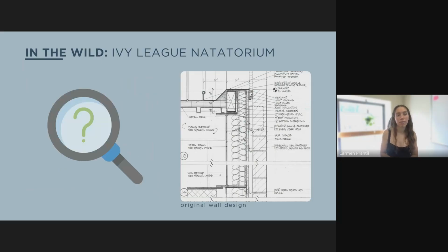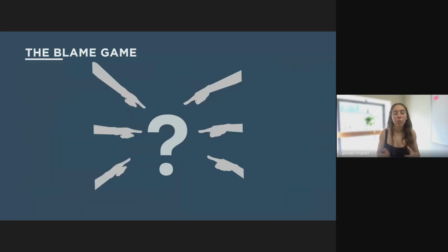So in terms of the primary contributor, which barrier do we think that this one was? So this one's going to be thermal control. Like I said, we have a significant amount of thermal bridging and not enough insulation at that base of wall condition. And when we see things like these case studies and premature building envelope failures or building envelope failures, honestly, in general, a very popular game for our industry is the blame game.